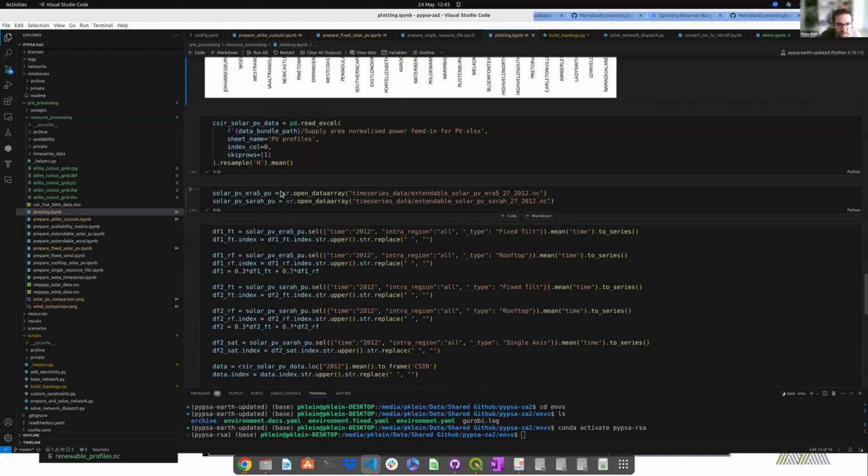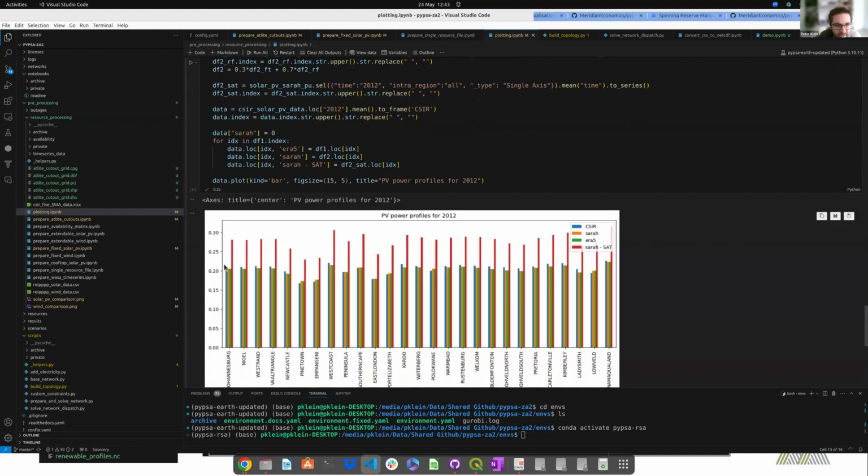And one of the challenges within the CSR Fraunhofer data is that the solar data is based on a mix. It's all fixed tilt and it's based primarily on rooftop solar with, I think, a 70-30 mix. So as far as I understand, that's the profile that the DMRE still uses in the RP, compared to if we're now looking at single axis tracking plants with much higher DC-AC ratios. You can see that those average profiles are significantly higher than the more dated Fraunhofer profiles.